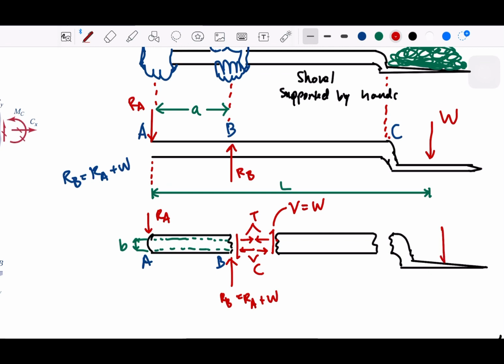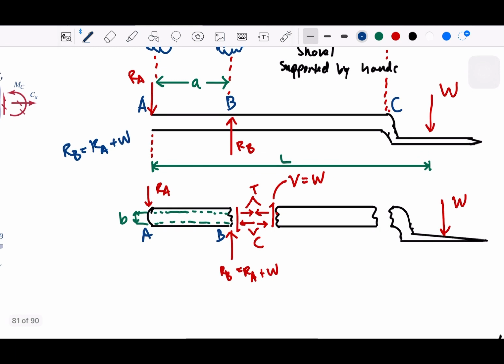And then this is weight, and then this is distance A. And then up through here, from this B, let's say B is here because it's cutting through that point, up until W, this will be L minus a. So we say that this is a free body diagram showing the resultants of all stress at the cross sections, right?